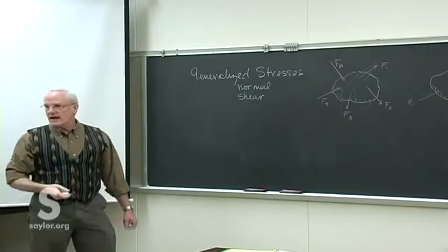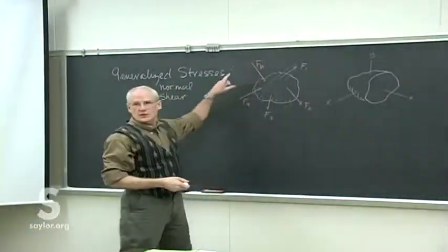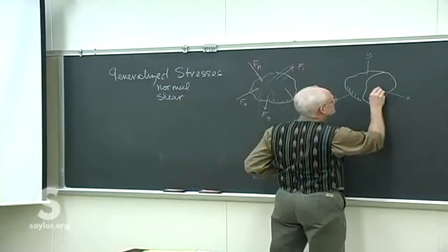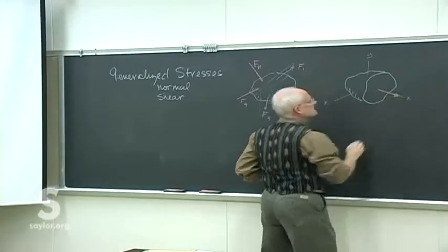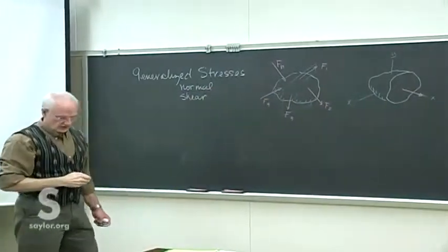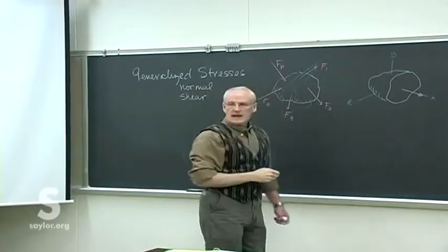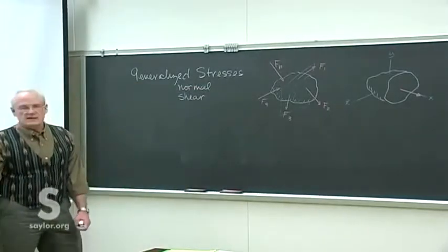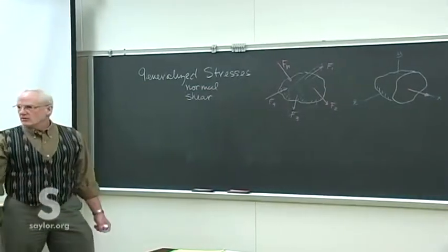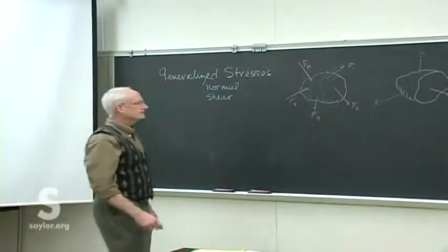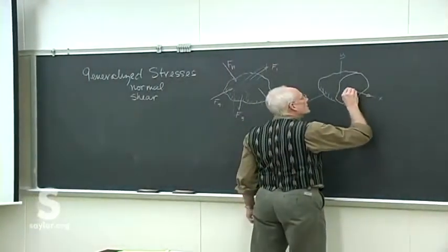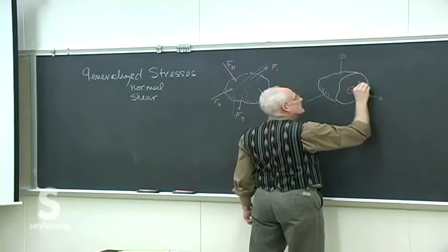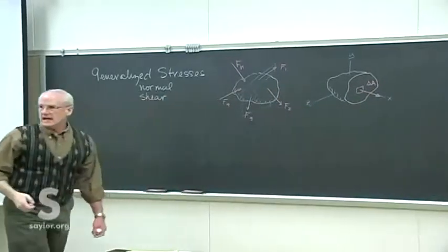So now that we've done that and taken all of these forces, figured out what the resultant is, we know that there will be some component of that resultant force right down the x-axis, normal to the face. That's just the nature of it: no matter what the resultant comes out to be, we could resolve one component of it to be in the x direction. So we'll also imagine that to be acting on a little piece of area we'll call delta A.